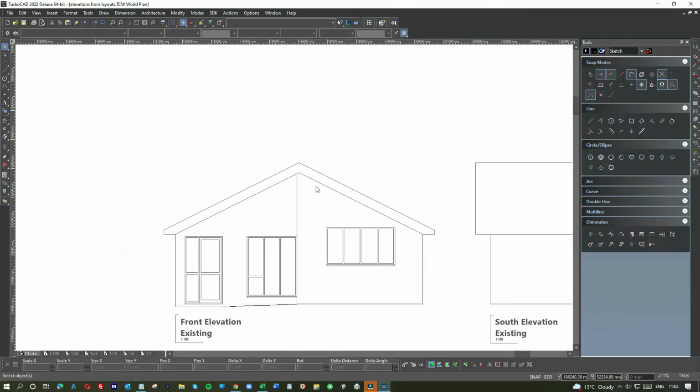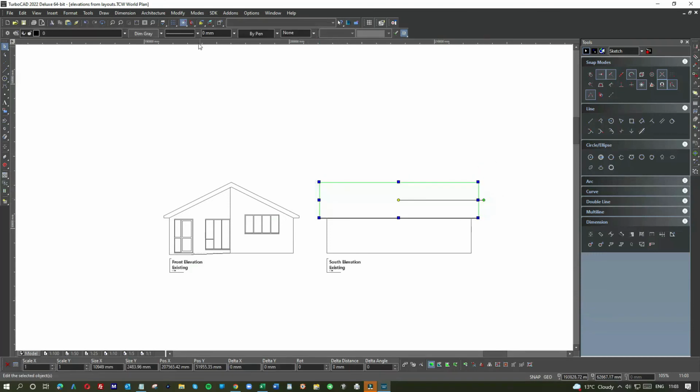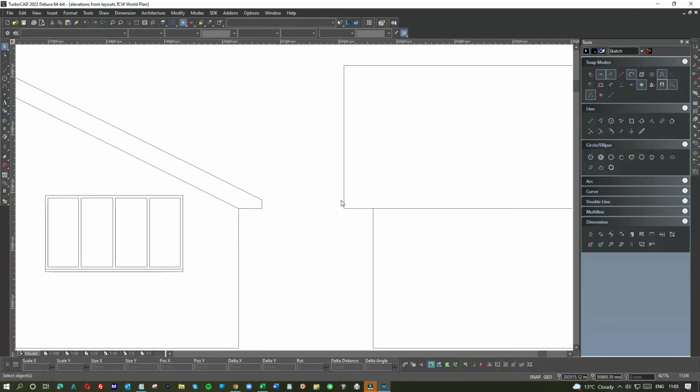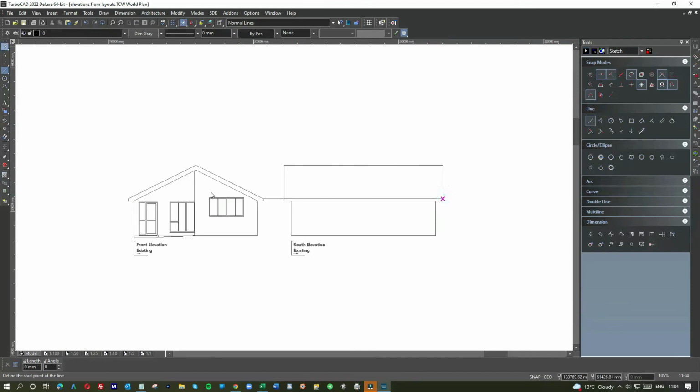Now something else we do. Where it comes to the roof outlines, like these three pieces here, what I would normally do is thicken up the lines just a touch. So whereas we have 1, 0, I will make 1. Likewise on the barge boards, make it. Now you are not going to see any difference on the CAD, but on the PDF when they blow it up, these lines will be represented as heavier. This one again isn't quite represented properly, because we need a fascia board here, and the fascia board kicks in. So do the fascia board.